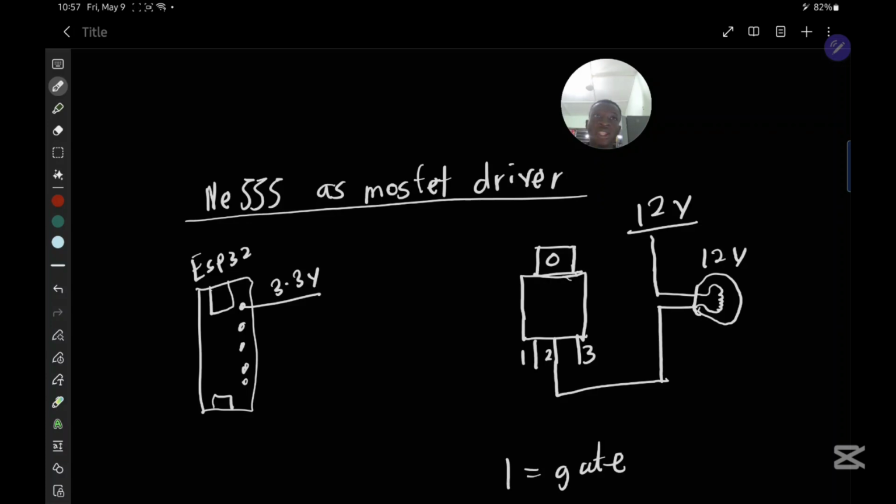So it's like these DC motors, some of them are rated 12 volts, but if you input 3 volts into it, it will spin, but it won't spin at its highest speed, right? But in MOSFETs it's different. It's the same phenomenon, but in this case, if we supply a lower gate voltage than the threshold, the excess power is going to be emitted as heat. So our MOSFETs can heat up quite a bit. In that case, the gate normally turns on fully at a certain voltage.